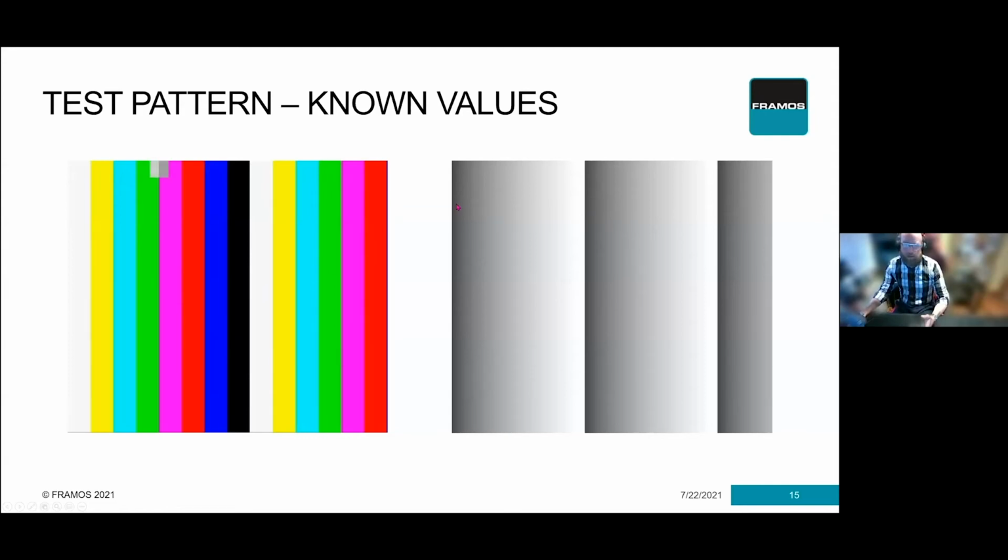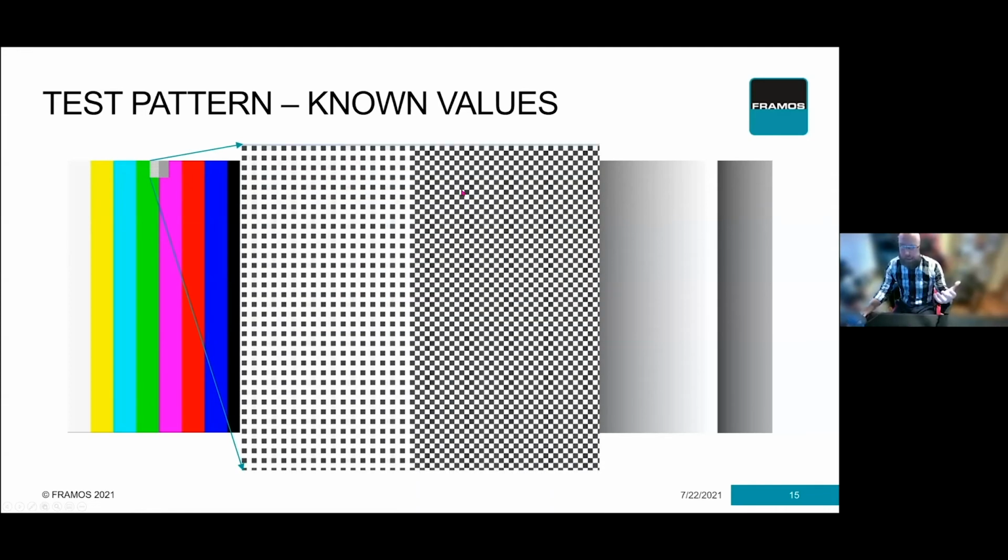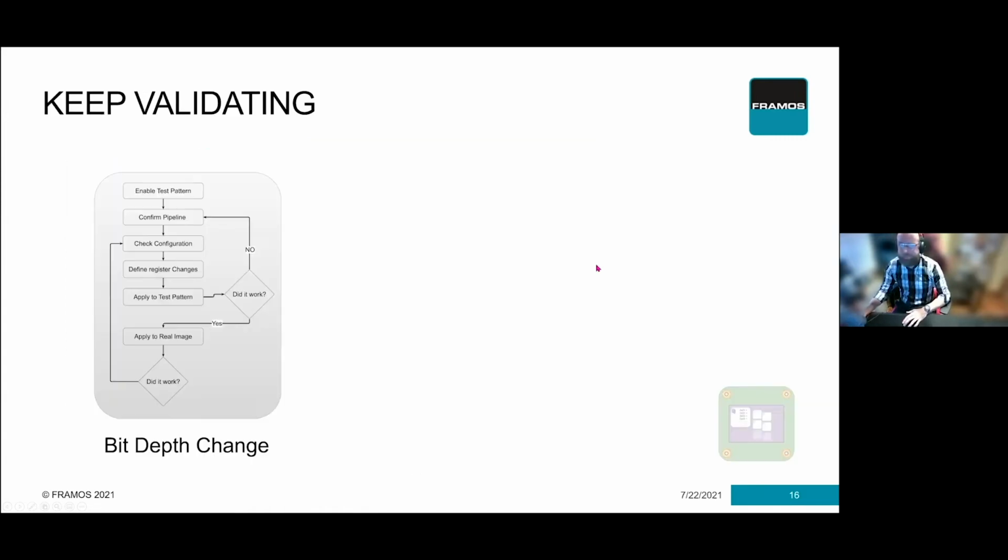Just very quickly, for those who may not know, we're always dealing with single values per pixel, in terms of grayscale values per pixel. A Bayer color image is still just a pattern of single valued pixels, where we have red, green, and blue, and we just use an average of all of those to create multiple values per pixel location. So this color image is still a monochrome image. I've just displayed it in this way.